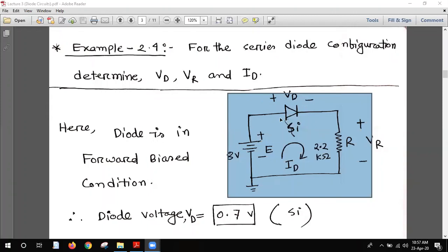Mustafa, I will answer your question, just give me 1 minute. You see that this is the voltage source, 8 volt. The current will start to flow from here. Always remember, when the current enters any kind of load, that side becomes positive, and the side the current leaves becomes negative.